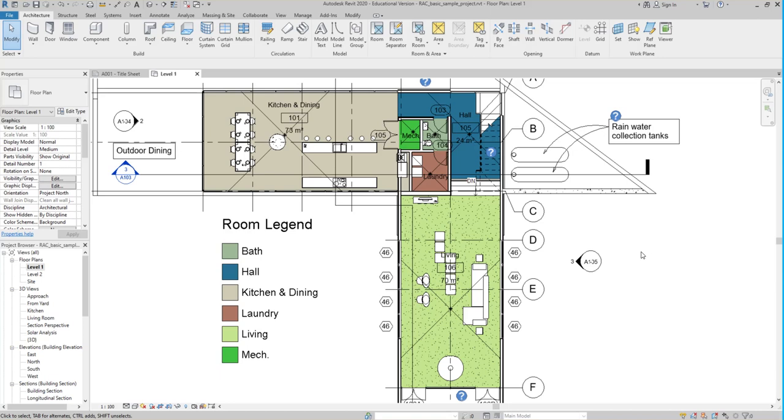We have a secondary level of objects that come next, okay? They're going to be maybe a little bit less important than those major architectural elements, okay? Things that go inside of the space, like maybe furniture, millwork, plumbing fixtures, things like that. Those are going to be slightly thinner pen weights, okay? Because we want those to be read second.